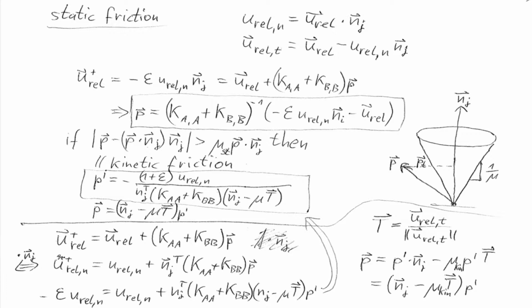So now this nu is the kinetic friction coefficient, and in general one chooses the same as for the static friction coefficient, but one could also use a separate one, meaning that it takes a lot of force to set the body in motion at all, to overcome this stickiness, but then the resistance will be rather low. That would be an option, but then it should be smaller than the static friction coefficient. Okay, but you can also just use the same usually. This gives already quite good results.